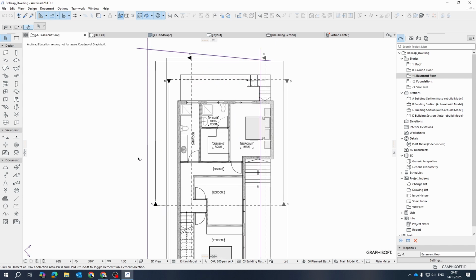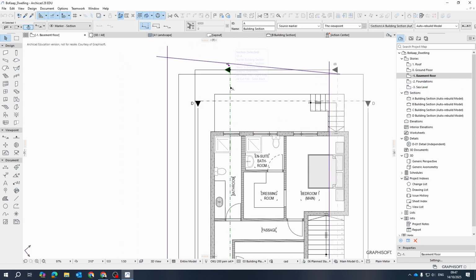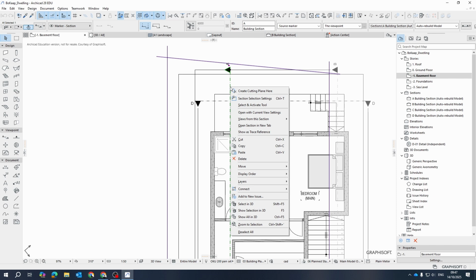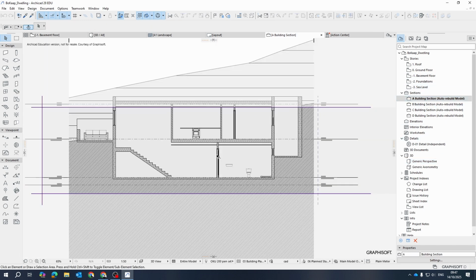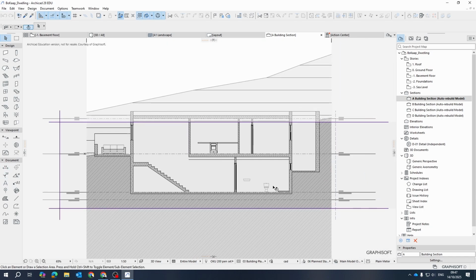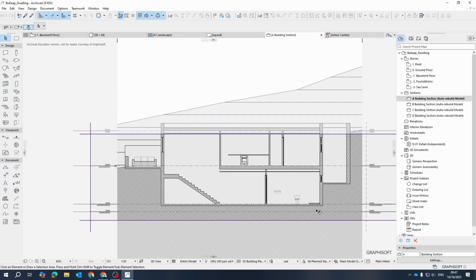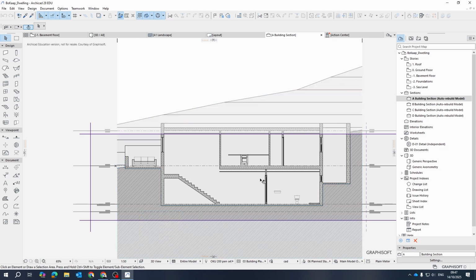Okay, so in a nutshell, if we go back to our sections, if you click on section AA, you can also go to section. So we want to go to section AA. So remember, once you've got your section established, you're going to use the drafting tools to add the additional information. You don't want to be modeling all of this information. It's going to take too long to model this information. Okay, so the outcomes for your project, just try and deliver those first,